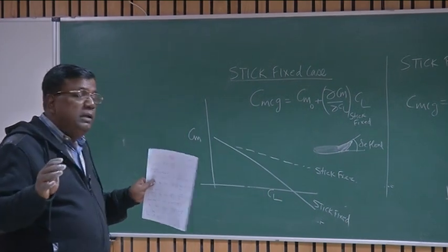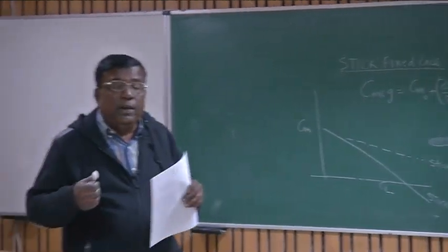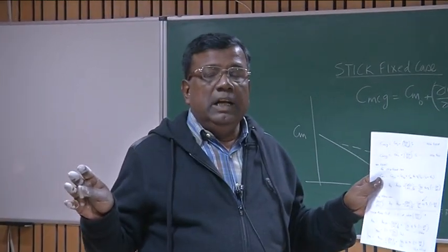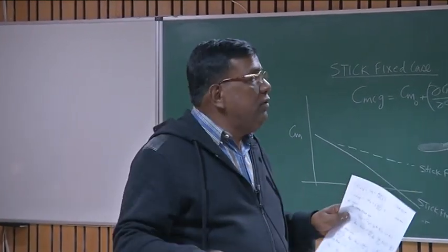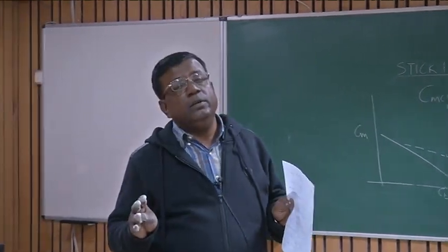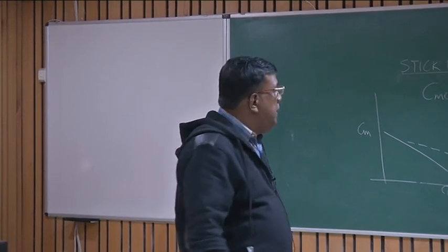I again repeat, somebody asked me a question: is the pilot flying stick free or stick fixed? Absolutely irrelevant question. The pilot needs to give a fixed elevator deflection to trim the aircraft at a particular CL trim. As simple as that. Okay?